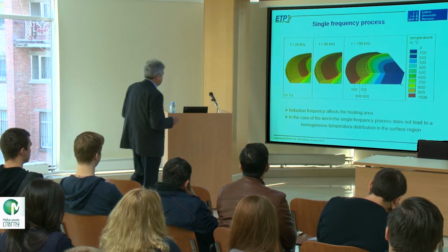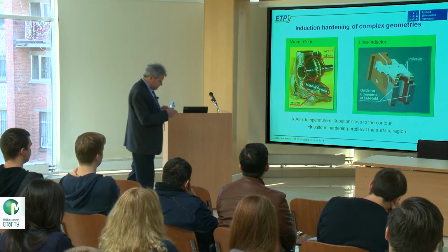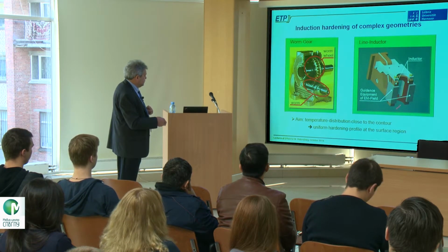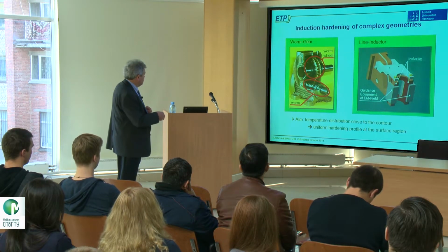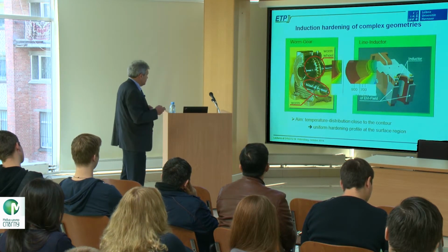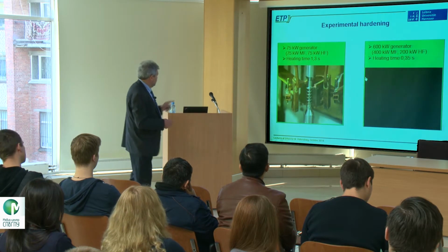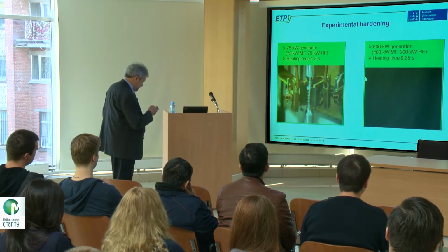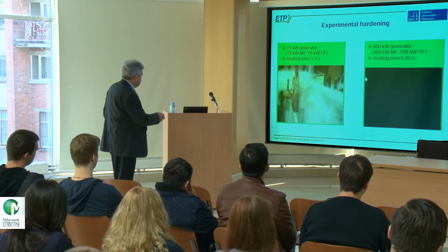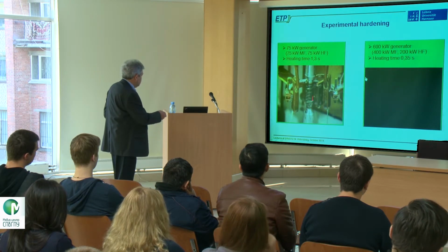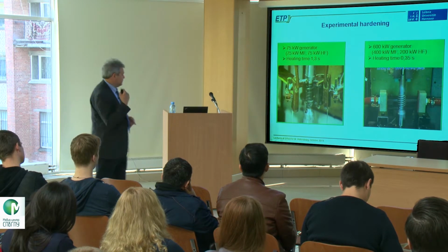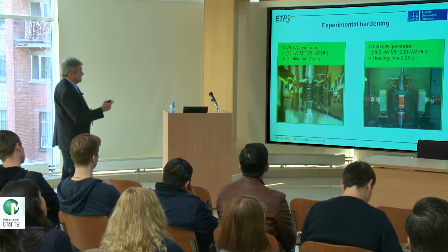So first we made, it's covered here a little bit, we have chosen a typical inductor, we call it line inductor. You see here, it has two main parts. It's a kind of linear inductor here, which is heating the sidewalls here. I go first again, you see here the worm gear is rotating, and the linear part of the inductor generates a current on this side, and a current on the other side. But due to rotating, of course, the heat which is generated is just distributed over the whole circumference.